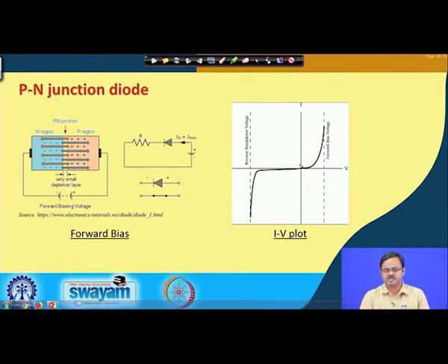At the beginning, I am talking about forward bias voltage. As I increase the voltage, there is some threshold after which I start measuring the current. What is this threshold? It is the threshold required to overcome the potential barrier that was there initially. So for a certain voltage range we will not be able to measure a current, but thereafter we will see an increase in the current value. Clear? And then as I keep on increasing the forward bias voltage, my current value is going to be higher and higher.